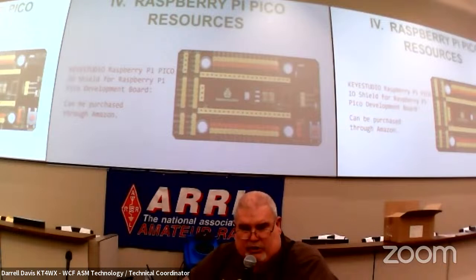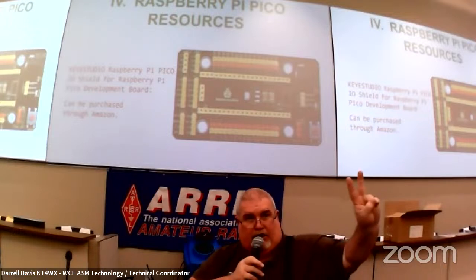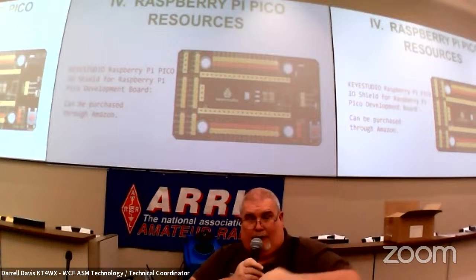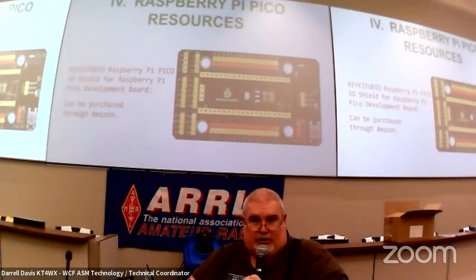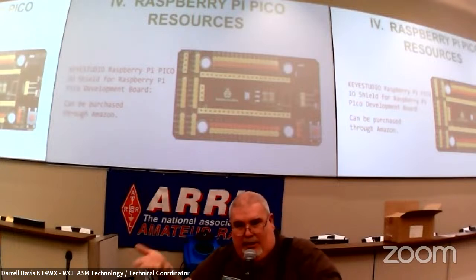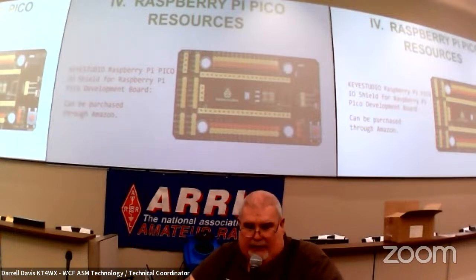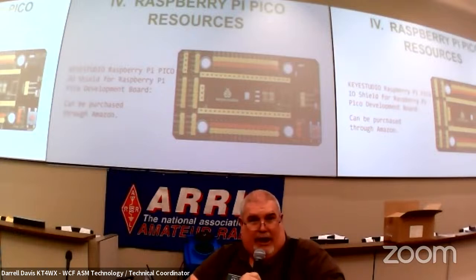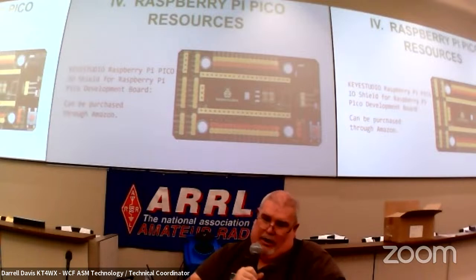And then when you design circuits, you know you have to run analog ground and digital ground. You have to be very careful. On these modern chips, you can get some VHF, UHF parasitic oscillations if you don't. But when you're breadboarding, you're probably not going to be worried about that too much for the purposes of this. But if you start getting up in the megahertz range, you have to be concerned about that. The length of your wires can add extra inductance and capacitance, and it can become an oscillator when you didn't intend it to.